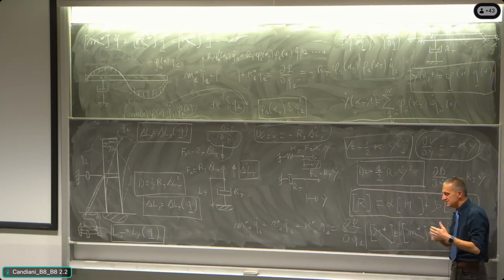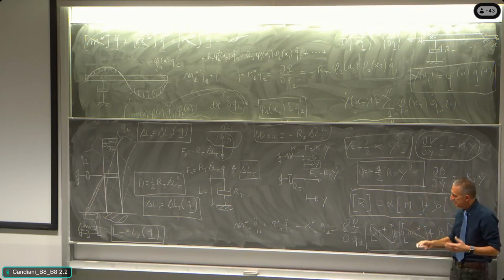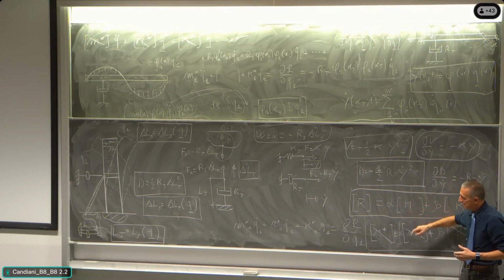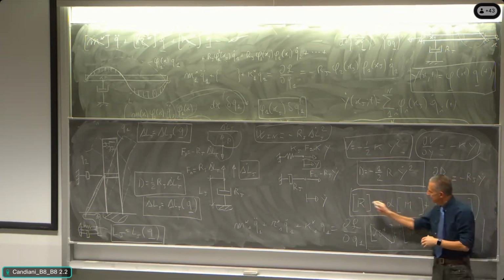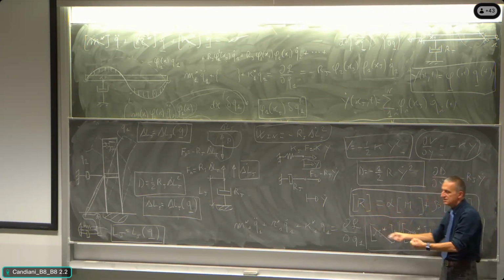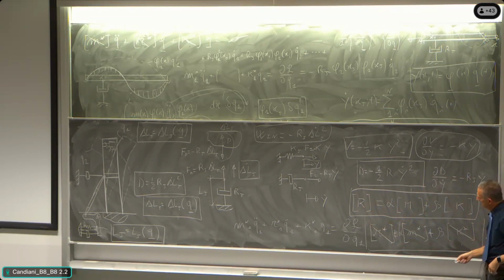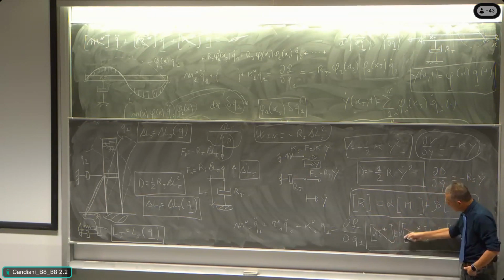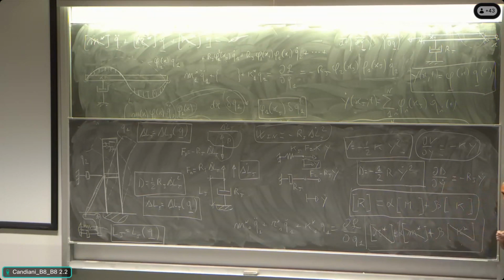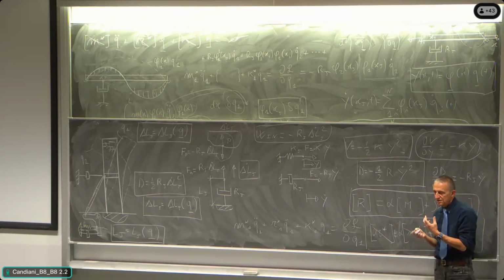All right, so I spoke on the two sides. The n degree of freedom, where you say, I have a full matrix of mass, a full matrix of stiffness, and then I get a full matrix of damping. And then in principal coordinates, in the continuum, we have a diagonal modal mass and diagonal modal stiffness. And we say, with the same rule, all right, diagonal damping matrix equal to alpha mass matrix plus beta stiffness matrix. It is the same, all right.